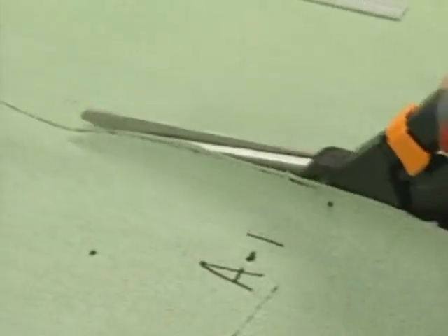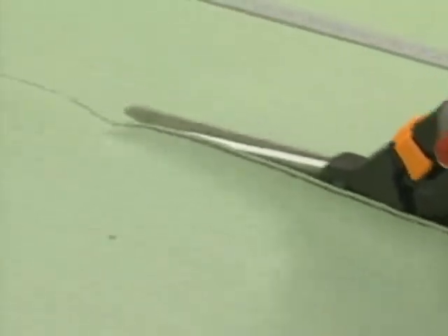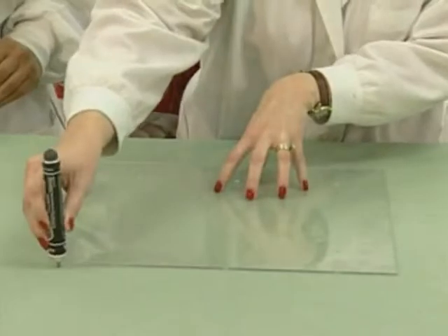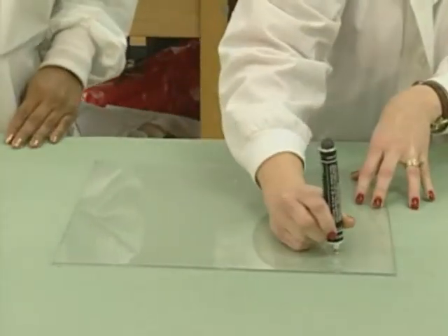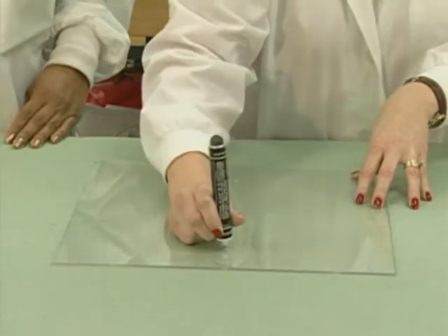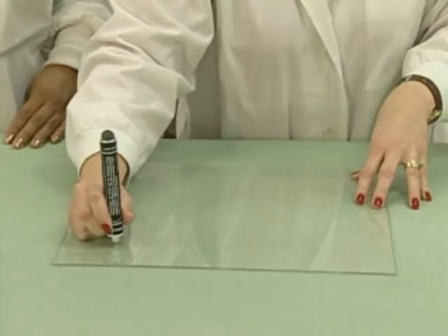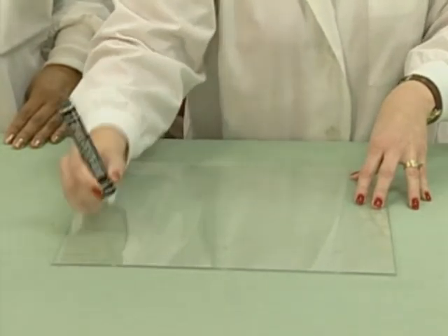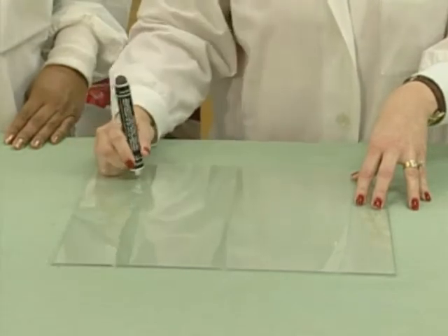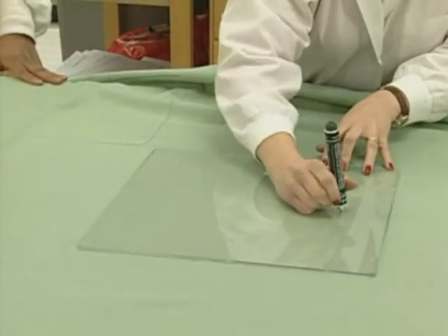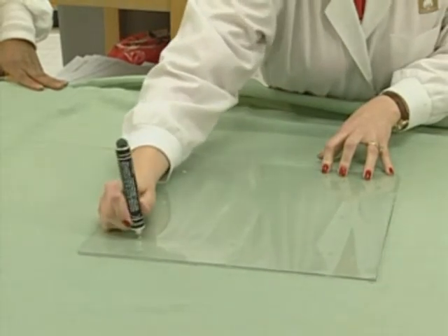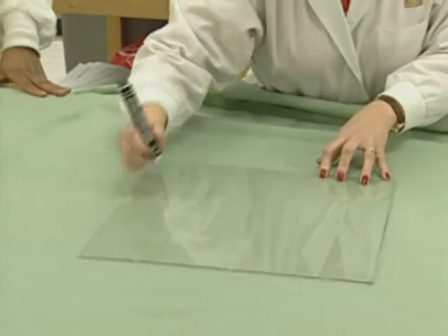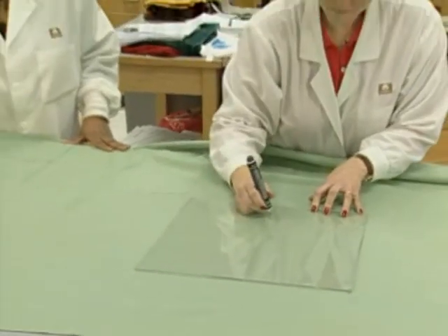Carefully cut out the specimens to prevent distortion. Mark each specimen with 3 sets of length benchmarks and 3 sets of width benchmarks using a ruler, a stamp, or other suitable device. Make sure the ink used is indelible to laundering. Normally, 10-inch benchmarks are used as they make the mathematics easier to calculate. Some tests call for larger benchmarks, which require the specimen to be larger than 15 inches square.